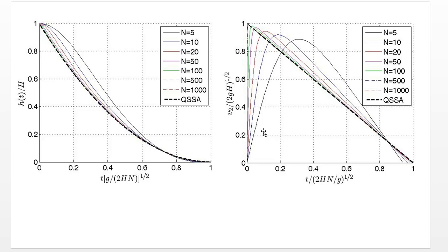What we can see, however, is that in the unsteady form of the mechanical energy equation, there's this initial transient period where the velocity goes from 0 at the initial time until it establishes a velocity that eventually becomes consistent with what's predicted by the quasi-steady state approximation. But once again, once n is close to 100, meaning the hole is 1/3 of the diameter or radius of the tank or smaller, there's very good agreement except for this very short initial transient period.